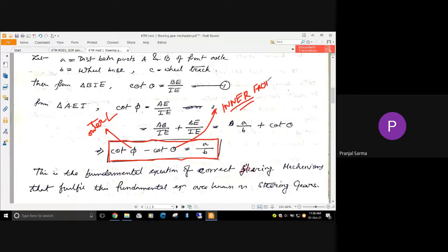In the Ackerman steering gear mechanism, the whole mechanism is situated towards the inside of the front wheel, so extra space is not required. Apart from that, the sliding pair problem was not there. Everything was a turning pair in the Ackerman mechanism. These are the two main reasons for which we prefer one steering gear mechanism over the other.